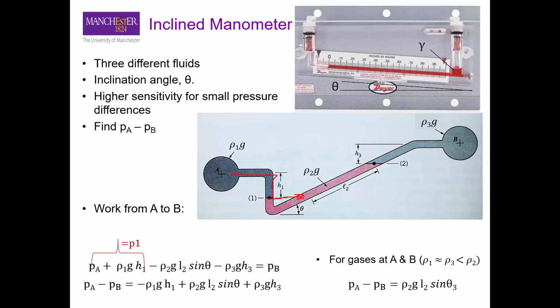Okay. So to calculate the pressure at point 2, we just need to use this length of the gauge fluid. Because we are going up, it means that we are going to decrease the pressure. As you know from hydrostatics, when we go deep, the pressure increases, but as you go in the upward direction, the pressure should decrease.